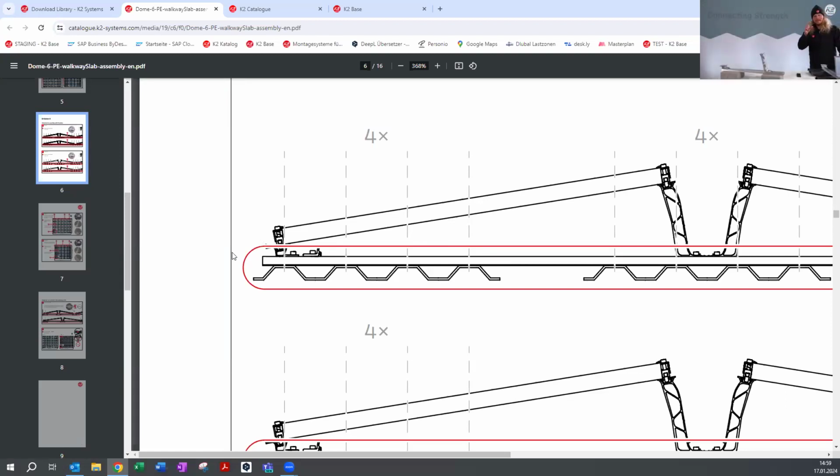Do you know if there's a maximum height for this gravel before it recommends as well? Yes, 7 is the maximum. You cannot type in more than 7 centimeters in Base. Well, it's in millimeters there, but 70 millimeters is the maximum height you can add in Base because it's not realistic anymore. Higher, you would be putting the gravel on top of the module. Okay. And in those cases, you have the other options of more PE plates or the extra stones. Exactly. Super.